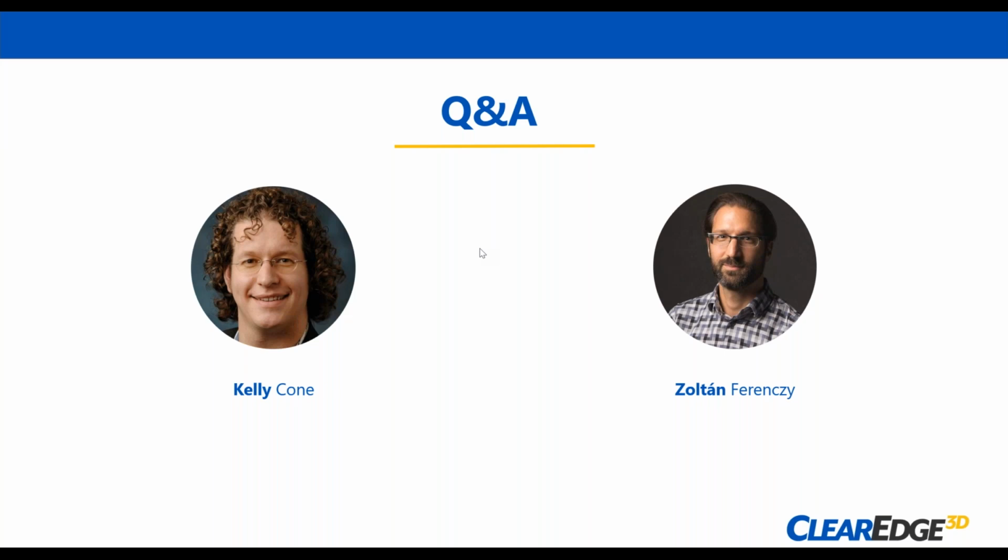Yeah, indeed. And we got this question, I think, from Jason. I think he asked it two different ways, actually. So can you set ranges of acceptable elevations for the point elevation report and for the contours as opposed to just one? And I actually think that's how it behaves. There's both a reference elevation and a tolerance, and that tolerance is what gives you that range plus or minus that reference elevation. Is that for the points as well as the contours, Zoltan?